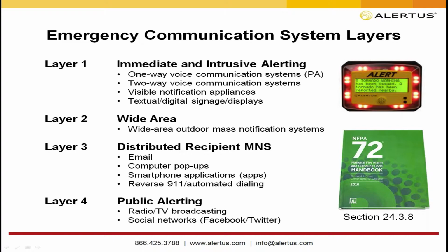And if for some reason you get into a location like manufacturing plants or military locations where the ambient noise happens to be over 100 dB, then they actually tell you to move away from an audible notification, because that would be too loud. People are not going to be able to tell it from the ambient noise, and that's why they move over to a visual notification. But the alert beacon does have the capability of having both.